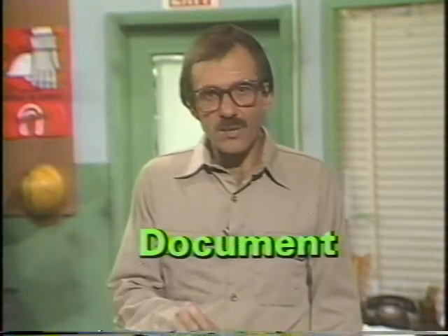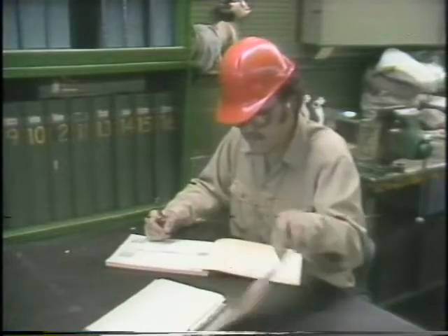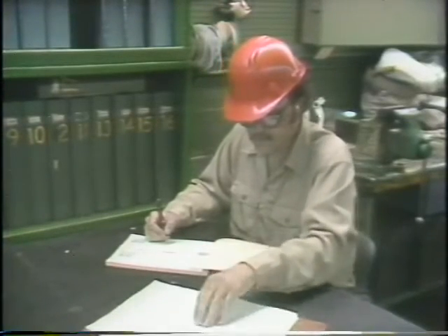Now, the last part of the troubleshooting procedure is to document the problem. Record what you've done to repair the instrument. Fill out the necessary forms and make entries in the appropriate records. For example, if you calibrated an instrument, make sure you update the instrument's calibration record. Now, nobody likes doing paperwork, but documenting the problem may help you or other technicians to solve any future problems that may occur in the system.